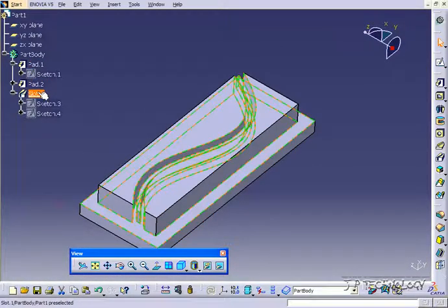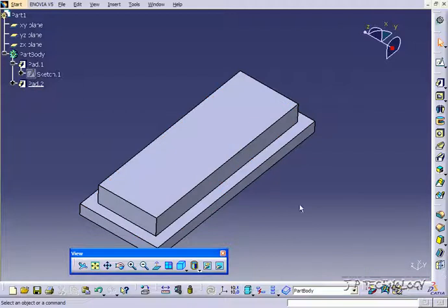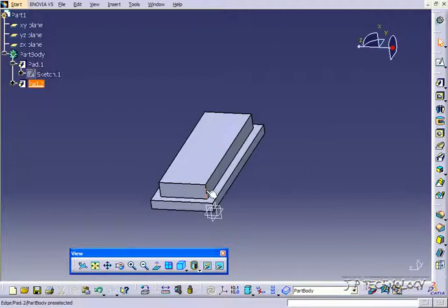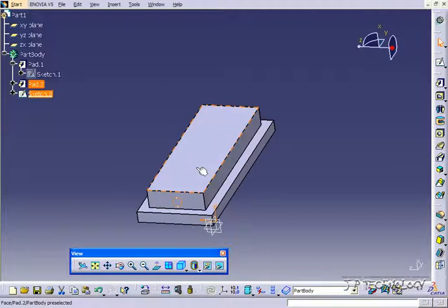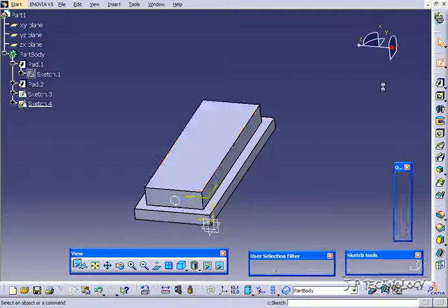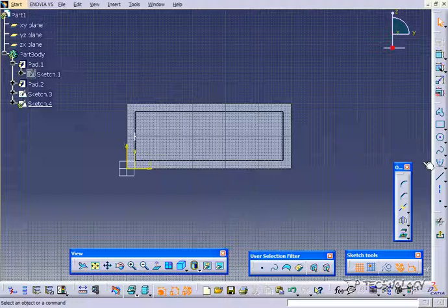Now let's delete this slot, and this time let's create one that isn't a square. So let's do a circle like we did on the last one. Let's click this face, click sketch, and we'll click circle. Just draw a little circle in there, and we'll go back, click the top face here, click sketch, and as we're going to be able to cut through this, we can make a route for it to follow. If we use the spline tool, you can make a little path and a little route, and everything's going to follow and cut right through it.